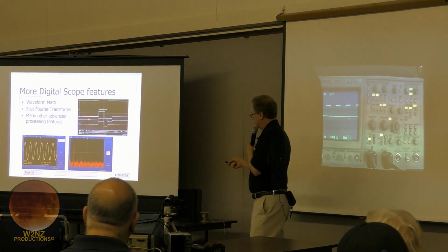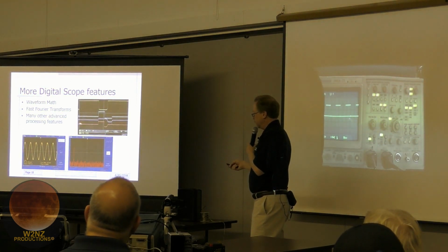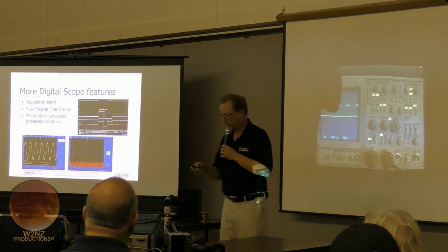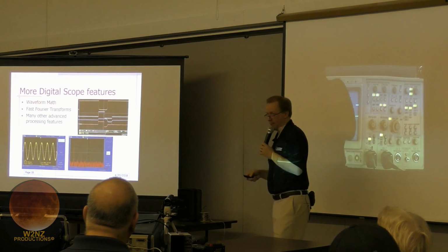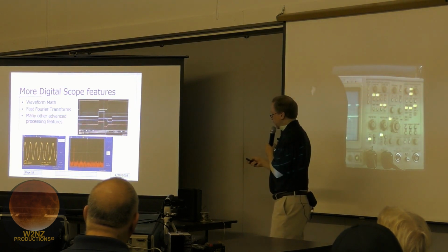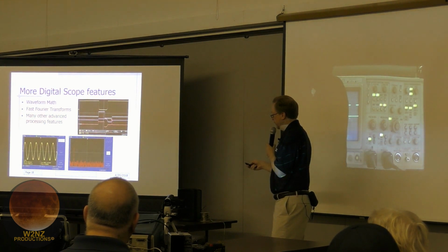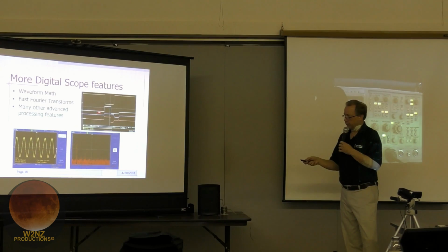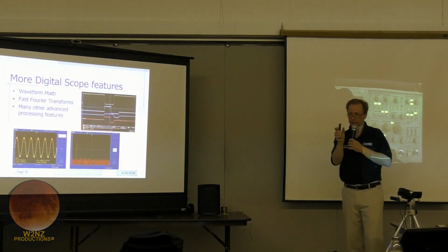Like this screenshot right here. If anybody's watched, I think the most recent video I did was on transistor switching times, and these are the waveforms from that. This is the collector voltage, base drive voltage, drive voltage into the circuit, base voltage, and this is a math waveform that takes these two voltages, subtracts them, and divides by the input base resistor.